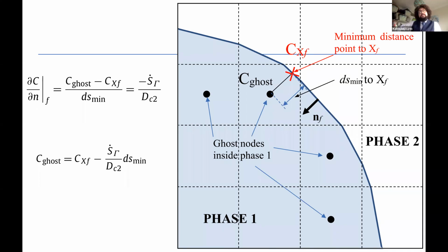Yes, actually. What happens is that we solve this as a single phase problem. So density, diffusivity, viscosity are a function of a Heaviside function, and will have one value there. We solve the Navier-Stokes in an Eulerian grid, as you can see here. But then you have tracking: a Lagrangian grid only on the interface, and the surfactant, the gamma, is solved only on the interface.